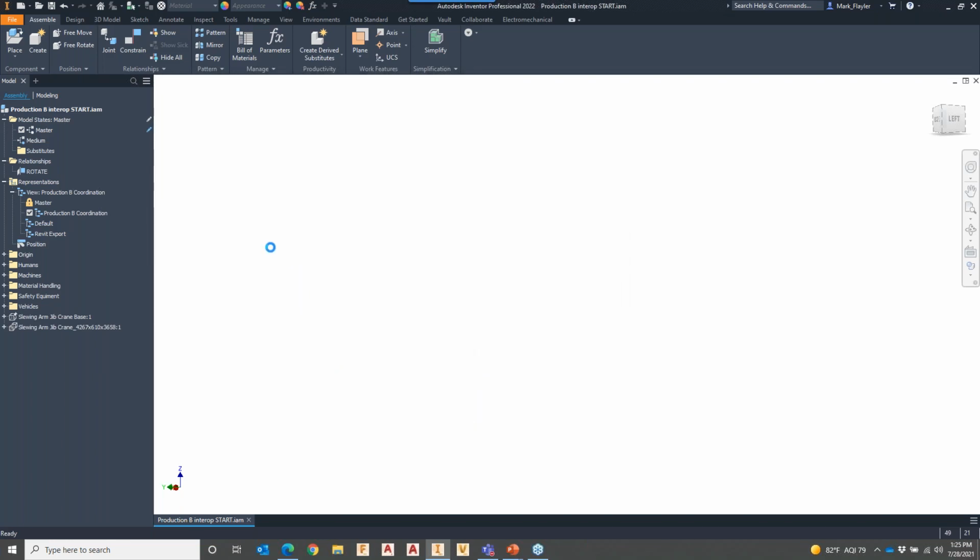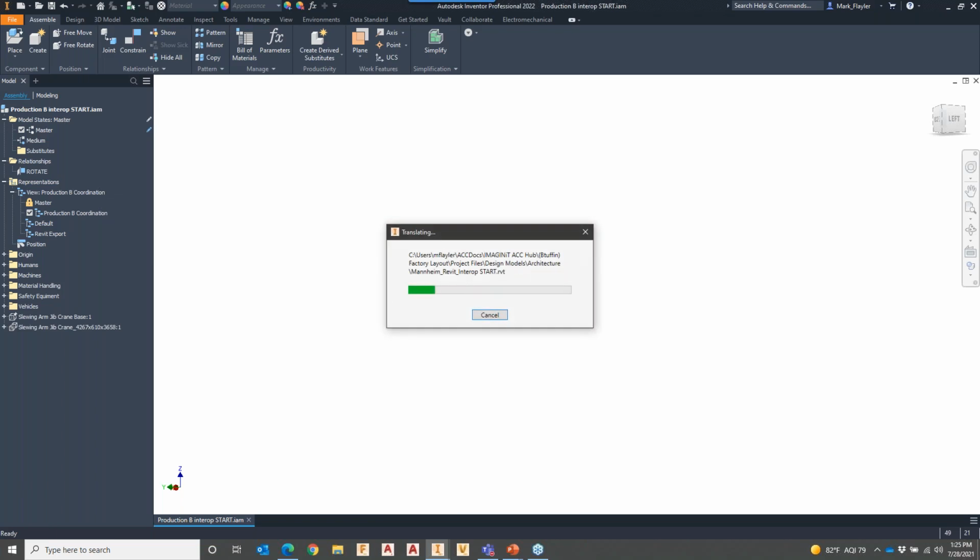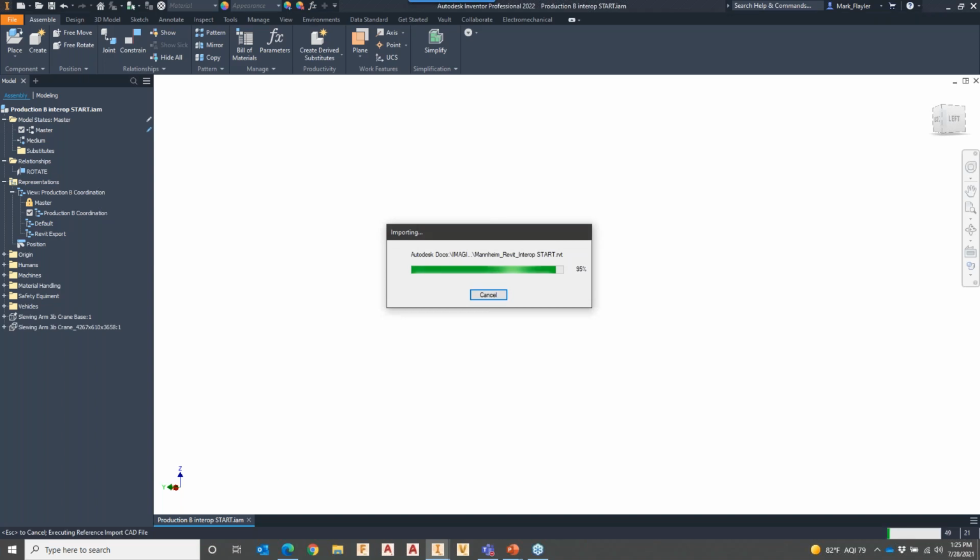The difference between reference and convert is pretty important for the AnyCAD technology. When you choose reference, it basically says, I'm going to constantly look on the hard drive to see if that model changes, and it's going to give me a lightning bolt that I need to update it, right? That exists for Creo models, for SolidWorks models, for anything, even a STEP file can be a reference model nowadays. So you can reference those, and if they change on disk, Inventor says that's changed, let's consume those changes that exist on the model.